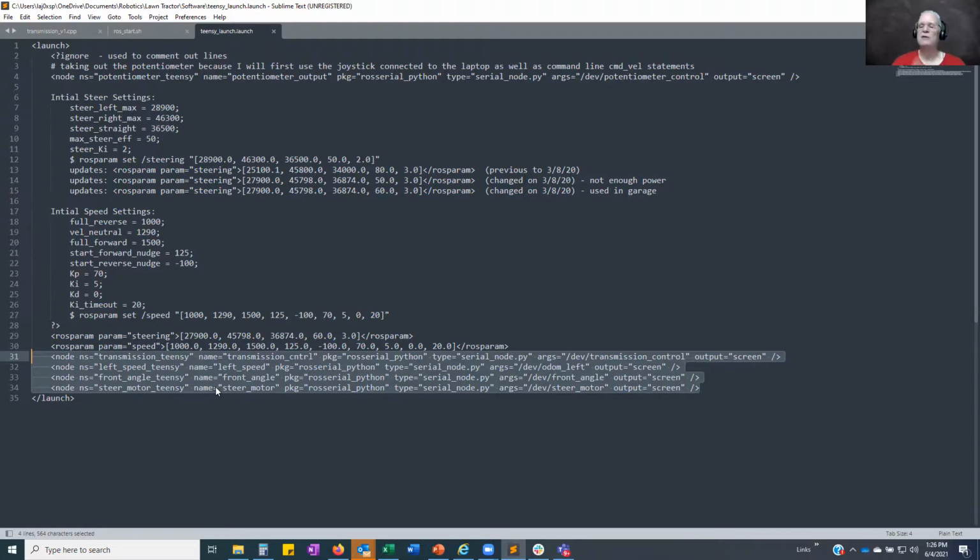I was noticing that on your system, it looks like you have the joystick plugged into your laptop, and then you've got the navigation software running on your RPi on your robot. When you do that, your joystick is physically plugged into the laptop, so the Linux driver grabs that and puts out whatever numbers it puts out. So your joystick node connects to that and publishes joystick topics.